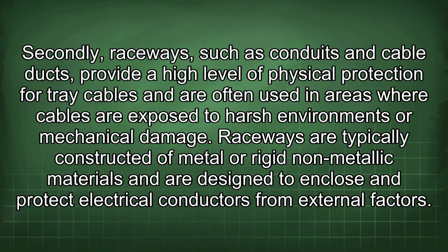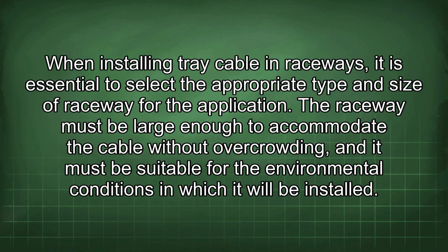Secondly, raceways, such as conduits and cable ducts, provide a high level of physical protection for tray cables and are often used in areas where cables are exposed to harsh environments or mechanical damage. Raceways are typically constructed of metal or rigid non-metallic materials and are designed to enclose and protect electrical conductors from external factors. When installing tray cable in raceways, it is essential to select the appropriate type and size of raceway for the application. The raceway must be large enough to accommodate the cable without overcrowding, and it must be suitable for the environmental conditions in which it will be installed.